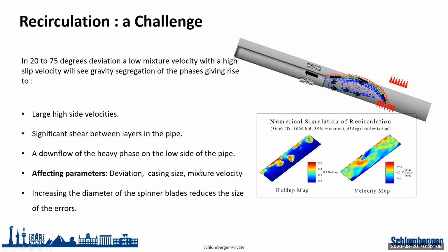Of course, this water recirculation is going to be dependent mainly on the velocity of the flow. It's going to be dependent on the heavy phase itself. It is also going to be dependent on the diameter of the pipe. So typically recirculation is going to be more obvious whenever you have large pipes, big size of pipe, and you have low velocity in the wellbore, yeah? In wells, for example, that have low production and you have a big casing, it is very common to see recirculation effect.